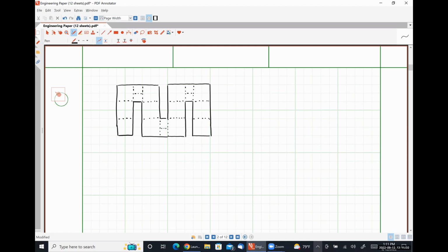So if current were flowing into this terminal and out of this terminal, our corners would experience a slightly different current density as the electrons move around that serpentine path. So typically speaking, the corner has a resistance that is about 0.6 R square times the normal square device.